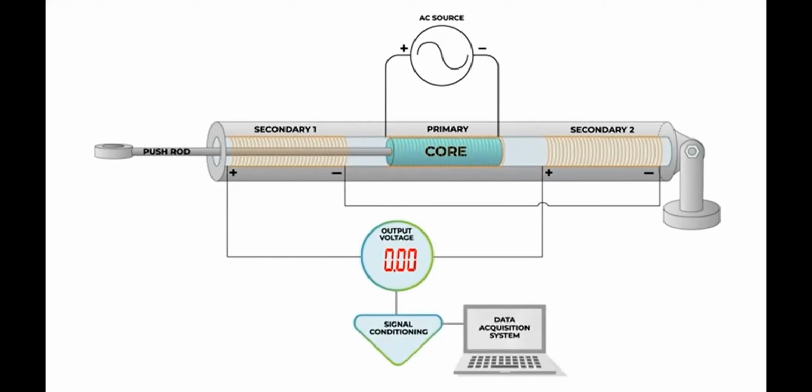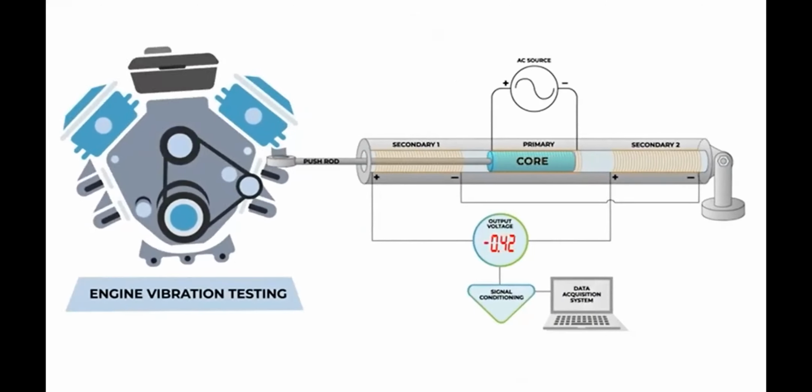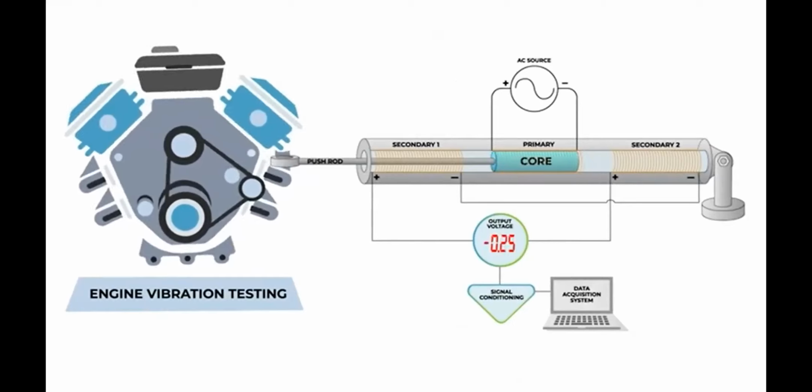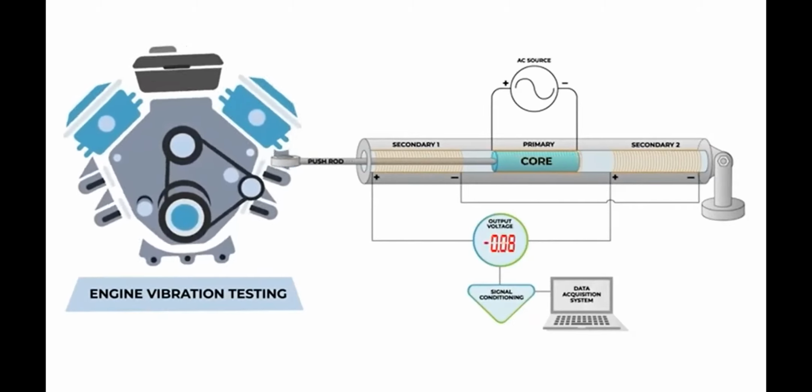This differential design gives the LVDT significant advantage over potentiometer-type devices. In an LVDT, any movement of the core causes a proportional change in output, giving it infinite resolution, limited only by the external output electronics.